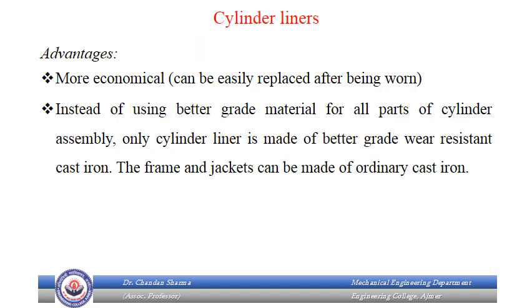Now the primary advantage of cylinder liner is they are economical. Just imagine, in absence of cylinder liner, we need to take the whole cylinder of some superior material.